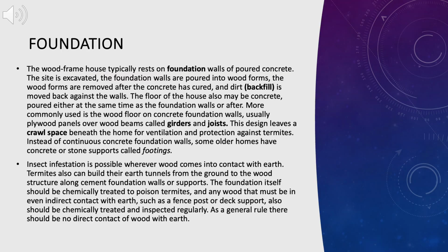Foundation. The wood frame house typically rests on foundation walls of poured concrete. The site is excavated, the foundation walls are poured into wood forms, the wood forms are removed after the concrete has cured, and dirt, called backfill, is moved back against the walls.